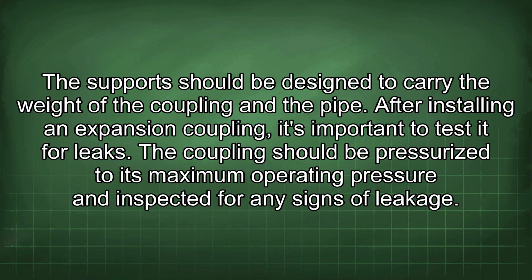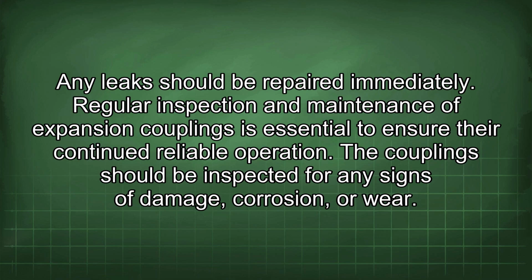After installing an expansion coupling, it's important to test it for leaks. The coupling should be pressurized to its maximum operating pressure and inspected for any signs of leakage. Any leaks should be repaired immediately.